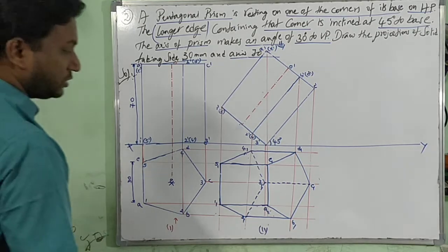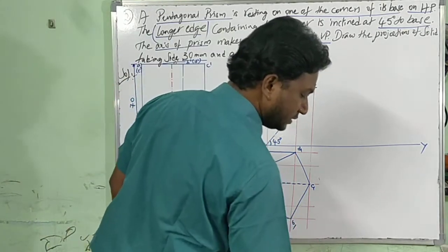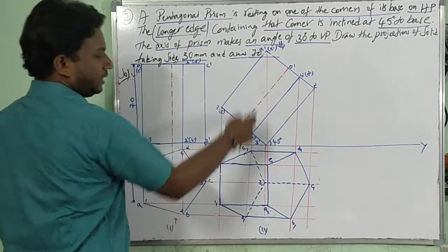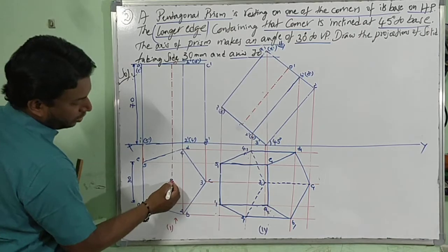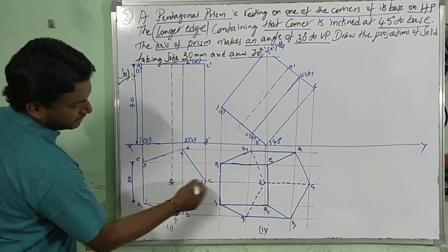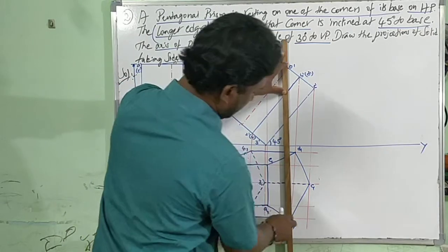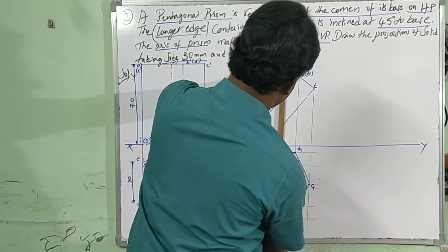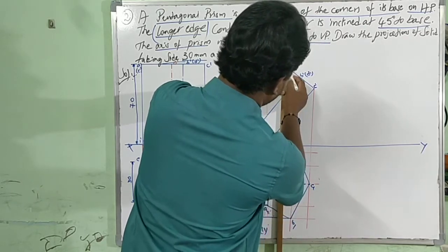Right, here you are supposed to draw the axis line also. How can you draw the axis line? From here project bottom. See, already from O, C is in line. See, let me show you. From O dash, I am drawing a vertical projector.